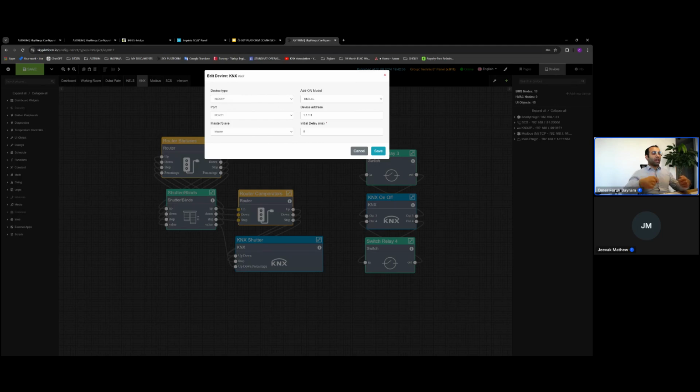After turning on again, all KNX devices will ask for status on the same bus. We don't want that. So if it's a crowded network, for example, we can select 1 or 2 masters. When someone asks, KNX devices will broadcast. So all devices, all slave devices as well, will receive feedbacks. So no need to activate every KNX device as master.